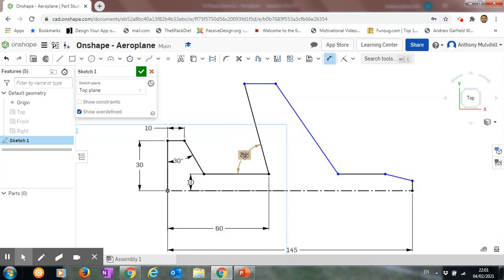Now let's say I made a mistake with that and it was meant to be 70 degrees. What you could do is double click on the icon in here, and it'll allow you to change the degrees. So look, I could do 70 and enter, and you can see it's after changing, but I know it's meant to be 75, so I'll double click again, and that is 75. And we can see the wing change with that.